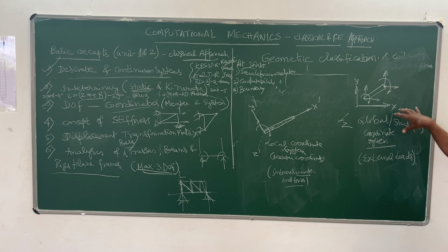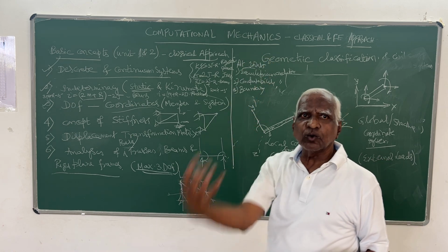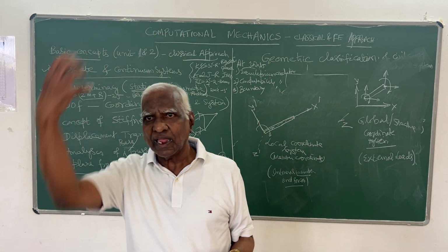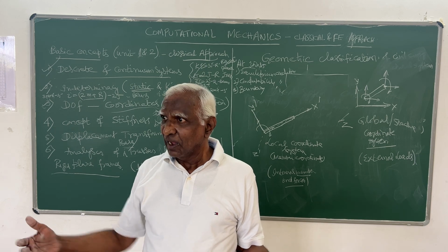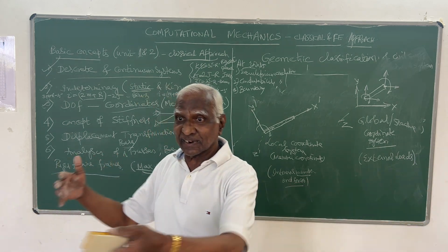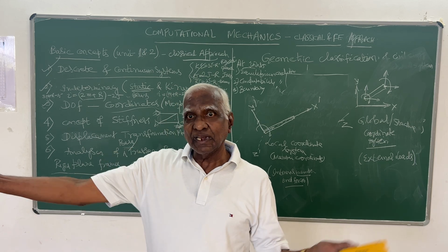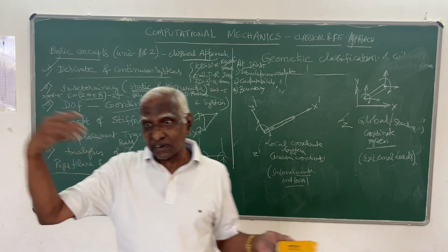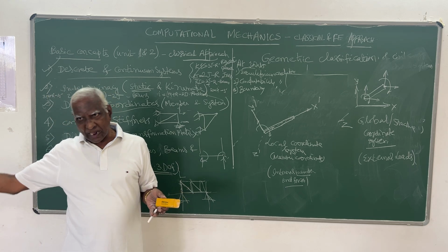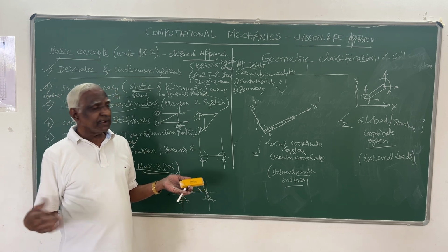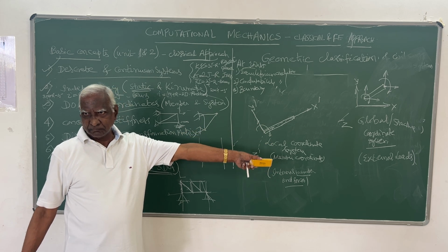So when we consider external loads in the global direction, because all loads are gravity loads, they act in the gravity direction. Wind loads may be in any direction, which we have to take normal, sideways, in any direction. Whether it is an earthquake load, wind, or blast load, whatever type of load, we always resolve it along the global direction.